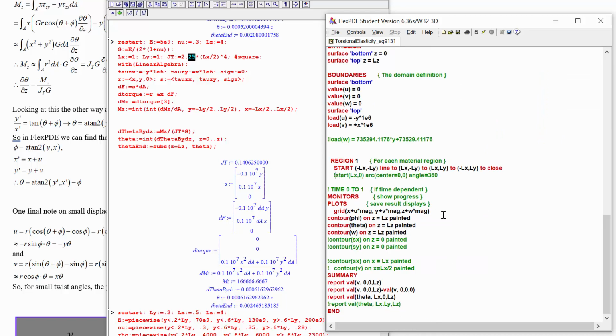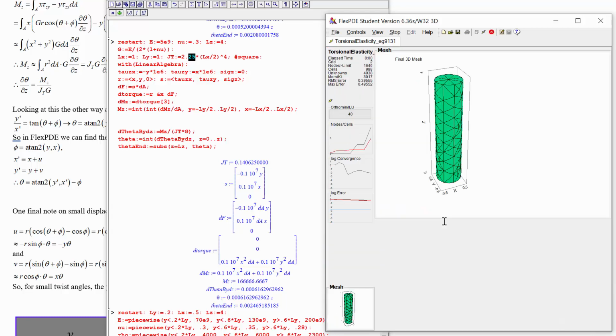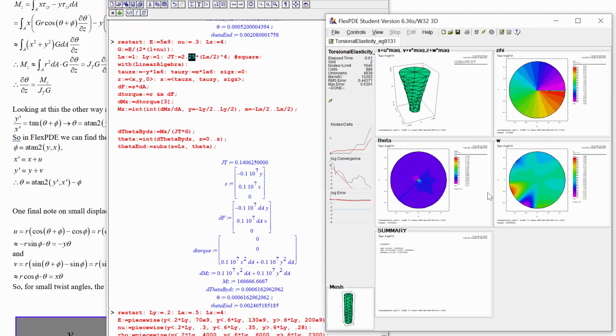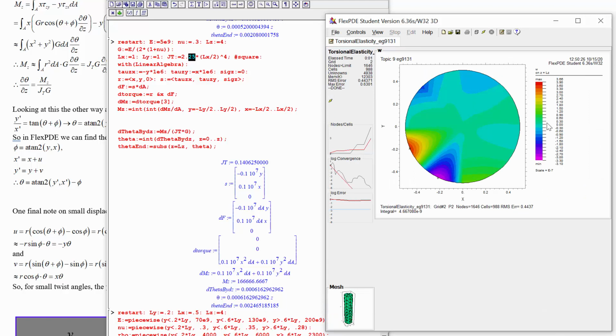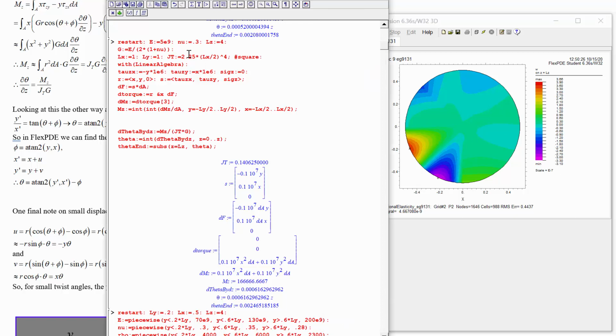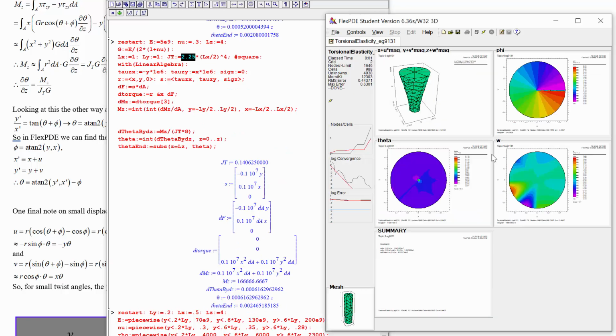circular cross section. So if we go back to the earlier version where we had a circle, then the displacement is a lot lower than that. We now have, according to Flex, some warping, but it's like 100 times lower than the previous one. It's not E-5 anymore, it's E-7. So this is a pretty good approximation for circular cross sections, but for square cross sections, that's why we have to use things like different torsion constants and deal with more complicated things like warping.